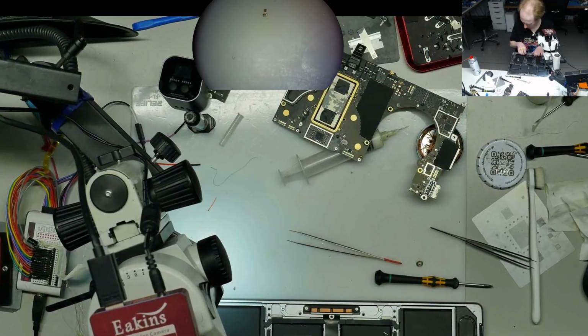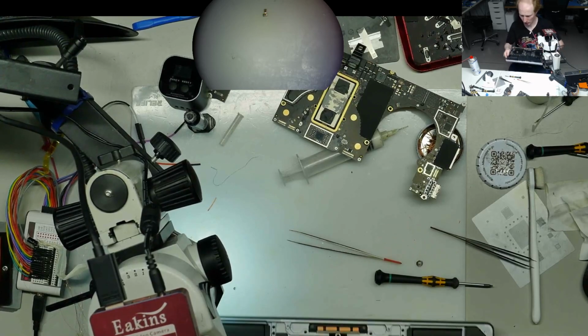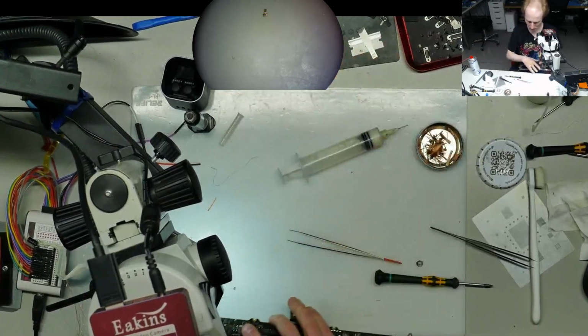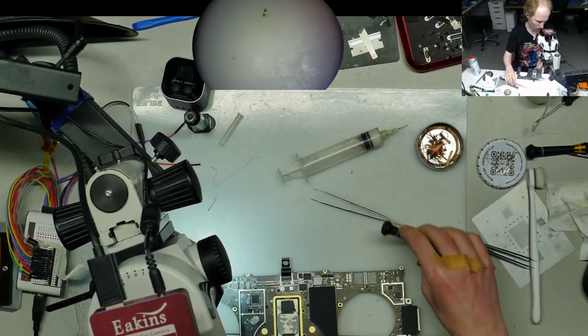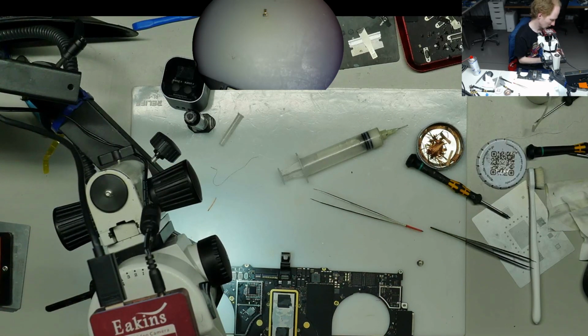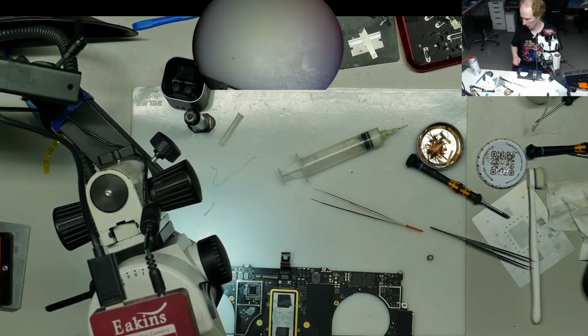Okay. So that's it for today. I hope that this will be useful, because you can use this I2C sniffing for all types of repair. Like if you're repairing charging circuit, you can also sniff what's happening here, audio amps and whatsoever. So you can always figure if something is not talking or something is not answering.